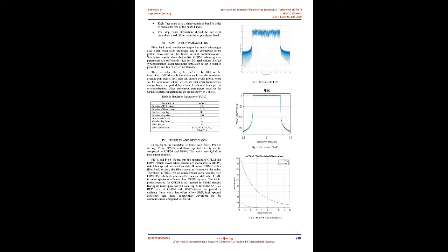In transmission systems, the Nyquist filter is generally split into two parts, a half filter in the transmitter and a half filter in the receiver. Then, the symmetry condition is satisfied by the frequency coefficients, equation 1. The frequency coefficients of the half-side filter obtained for K equals 2, 3, and 4 are given in Table I. The frequency response is obtained from the frequency coefficients through the interpolation formula for sampled signals given below. The impulse response h(t) of the digital filter is given by the inverse Fourier transform of the frequency response, which is given by equation 2.